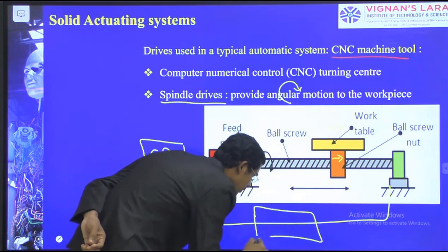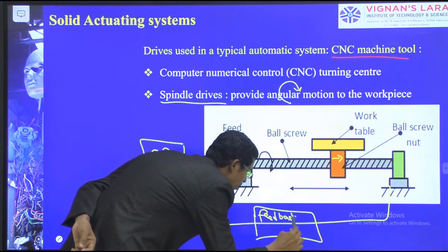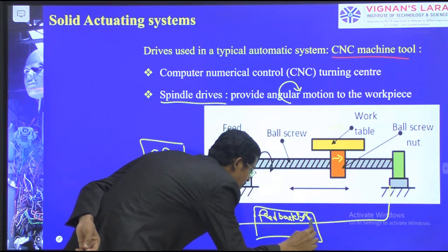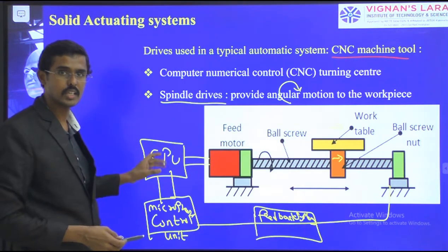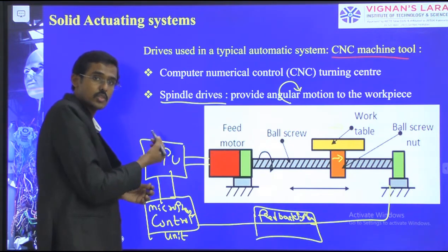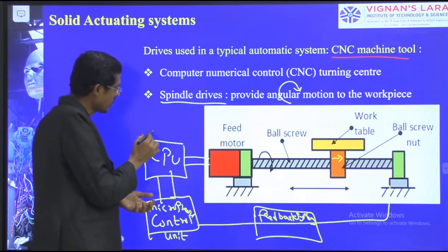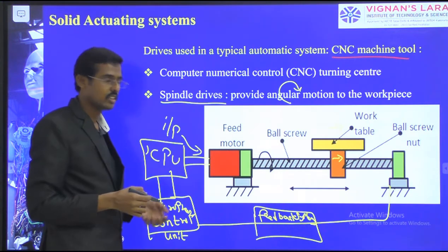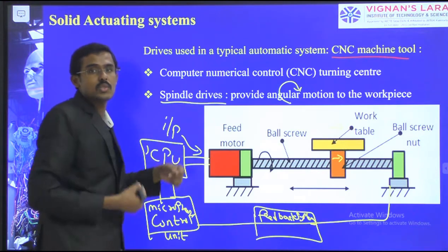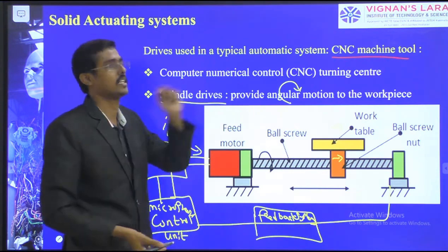I think we remember feedback. The feedback system is there, therefore we have taken the feedback to the control unit, which determines whether it has moved to the correct position or any changes are needed. In such a way the input connections are given again. Therefore, it is rotated again, reducing or increasing the speed of the spindle action.